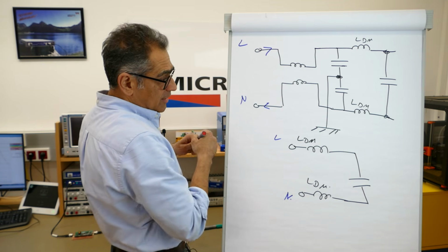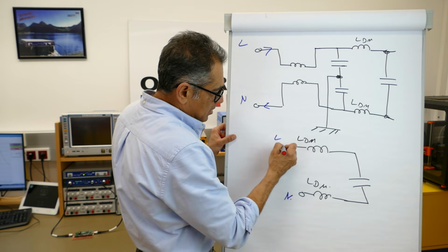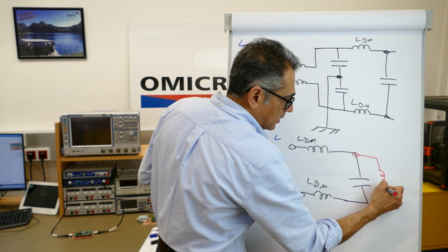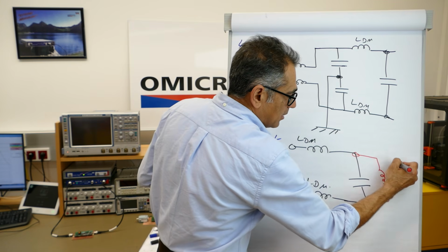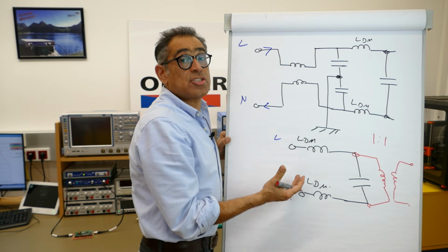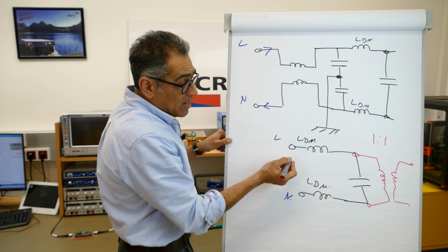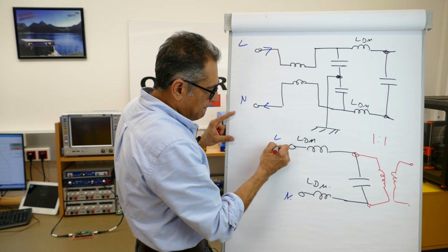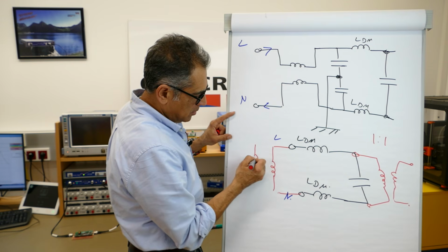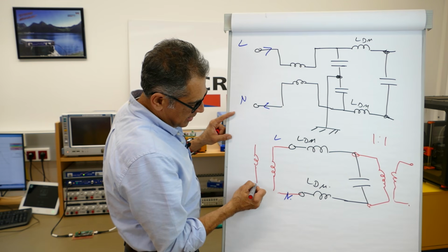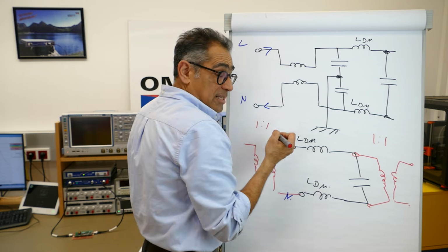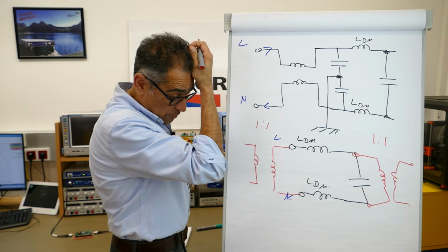So imagine that I have got a one-to-one transformer there. I'm isolating it effectively from there to there and from there to there. That's a one-to-one transformer that we actually call a balun, right? And then I need to put another one on this side. There we go. That is another one-to-one, identical to that one-to-one transformer. Again, it's a special type of transformer we call a balun.